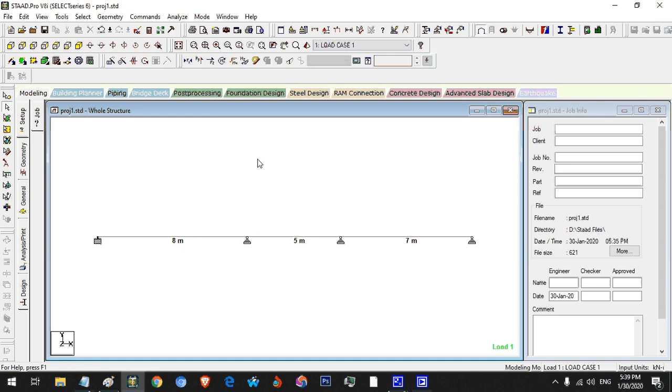The last information I want to add is when can you add pin or nodes like this? When? So the three options I remember is when you have different section, when you have different material, and when you have a concentrated load. This is all what I have for this lesson.